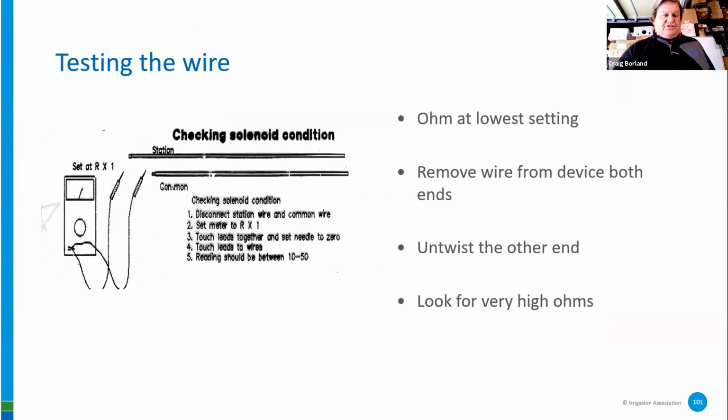So look for your resistance on the 2-wire path, in which case now you're going to go out there and cut the distance in half, go halfway out, go into that valve box, open it up, and check which wire has the short on it and work your way through.